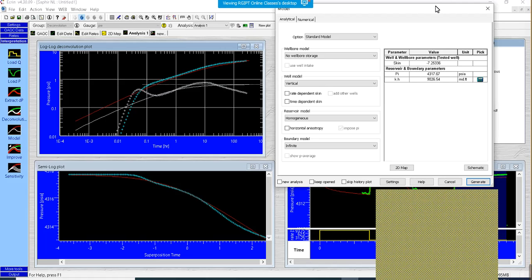So this limited entry zone thickness, the height of the zone from the bottom, may be given to you, because these are the constant things that may be given to you. So based on this data, I can understand, okay, I already have data. So instead of using a homogeneous model, let us use the two porosity, spherical, two layers, radial composite, linear composite.